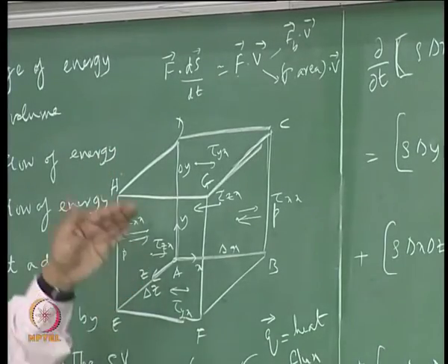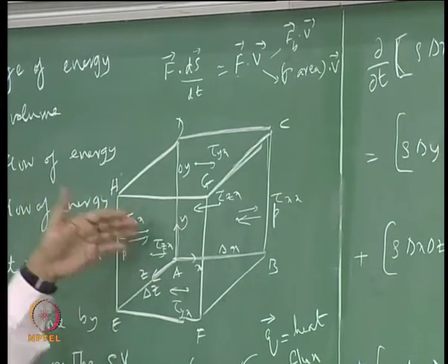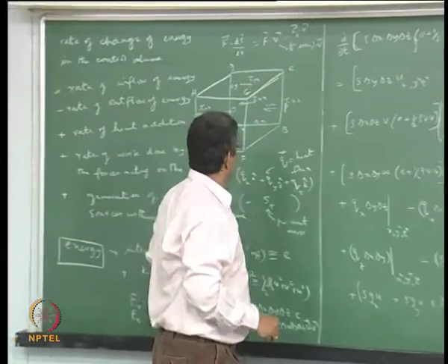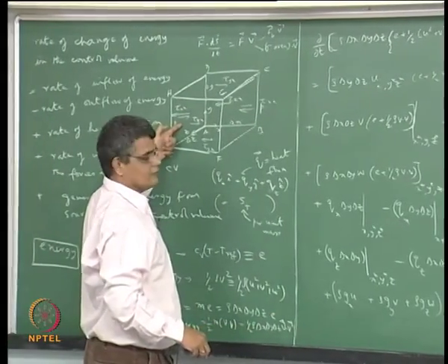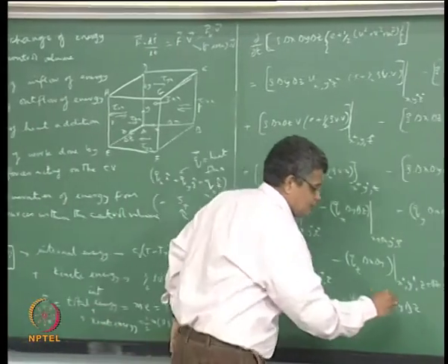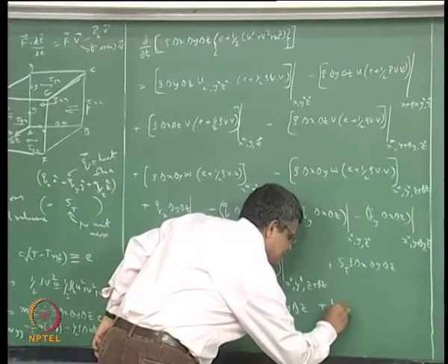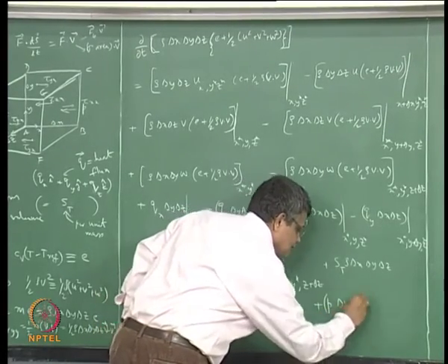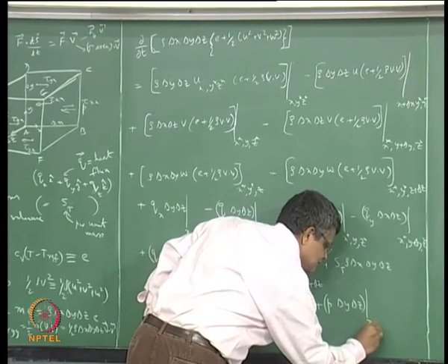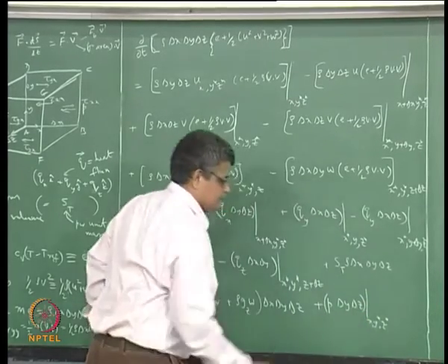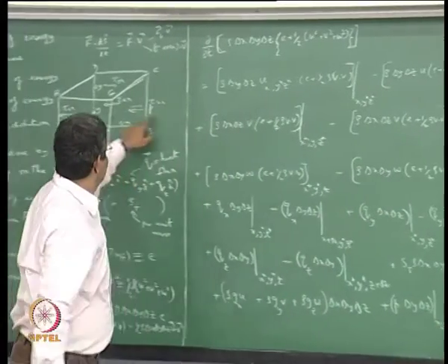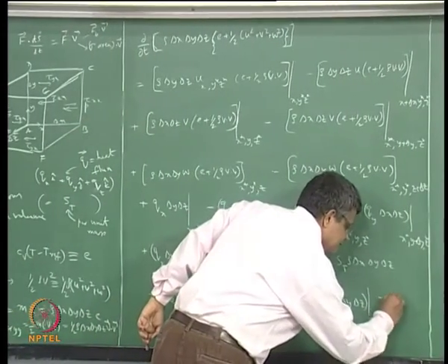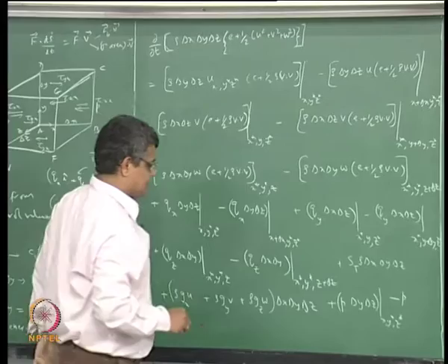So if you consider just the x direction forces, and out of that x direction stresses, and out of that the pressure as a stress acting on the x face, left face, the contribution is plus P times the area, which is delta y delta z, evaluated at x, y star, z star, and on the right face it is acting in the opposite direction, in the negative x direction.